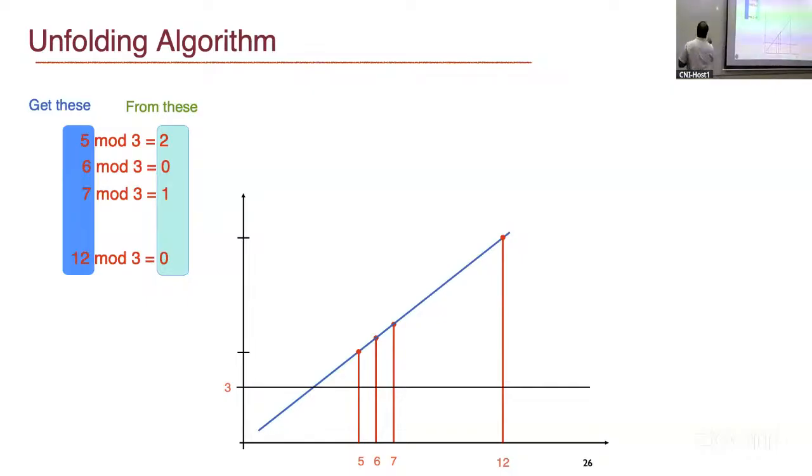If you keep sampling like this, it is general sampling, but let's say you are oversampling, densely sampling. If you see from here to here, the change delta is very small. Though I have a folded sample, I can guess the first one, and for the next one onwards, I cannot go too far from the original guess. With that, I can reconstruct the signal, but with some offset.